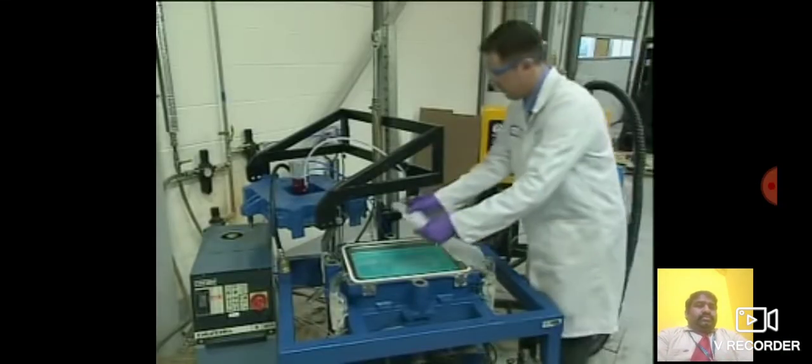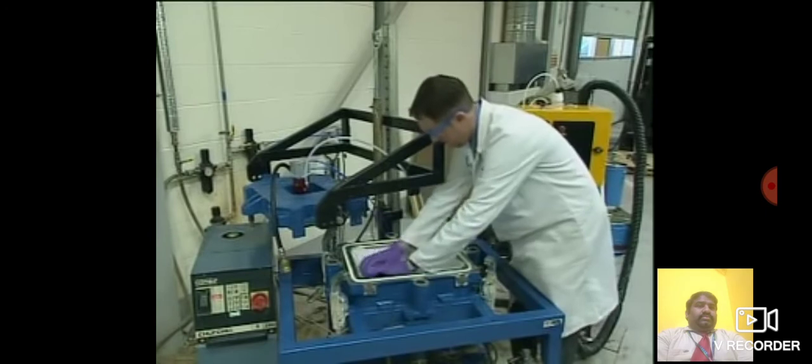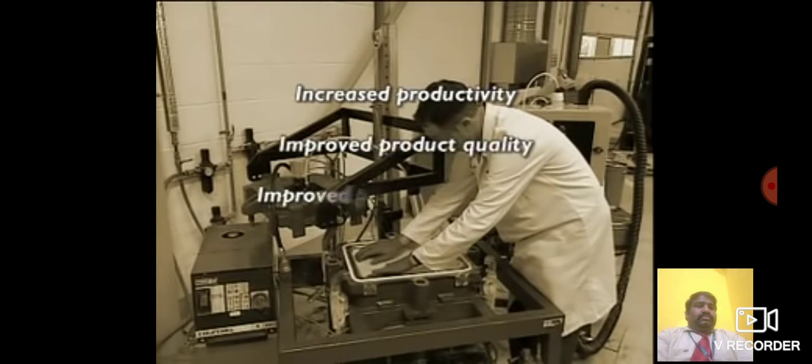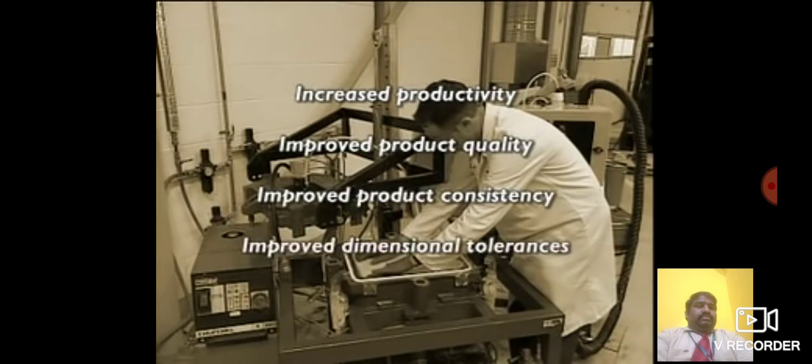RTM can offer distinct advantages, particularly if temperature-controlled tooling is used. Increased productivity through the use of higher injection pressures and heated molds. Improved quality. Improved product consistency due to better process control. Improved dimensional tolerances.